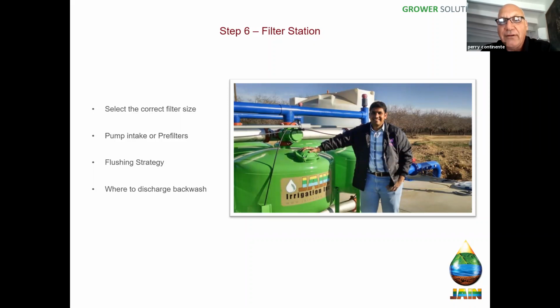And so what I like to do is calculate the additional pressure and flow that it's going to take, so that I can flush and I can also deliver the water to the field, so that we're never in a place where the uniformity goes down in the field because of low pressure, or the effectiveness of the irrigation is significantly less. It also gives you a perfect flush every time, because you have the same pressure, because the pump seeks the pressure that you need in order to make it work.